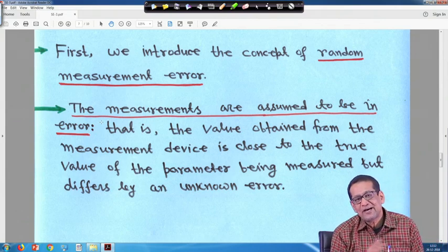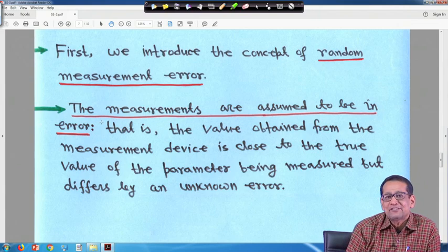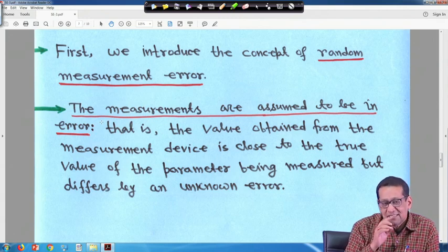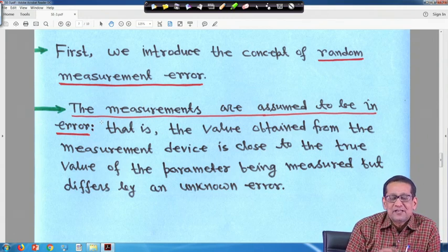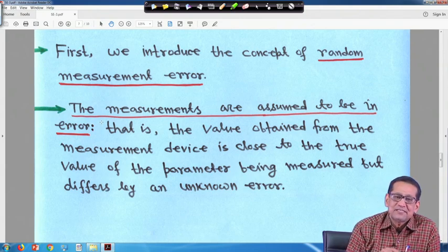Basically, you are taking the mean reading, right, because a true reading is there, but on both sides you will find the pointer oscillating. So, when it has settled down, you take the reading, which is basically the mean reading. And in the ammeter or voltmeter, just check, the instrument accuracy will be written somewhere. Suppose it is written that accuracy is plus minus 3%.